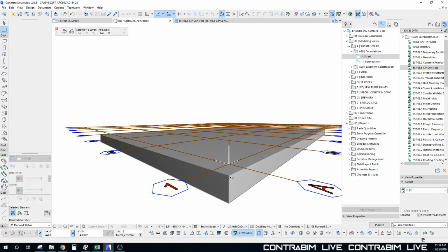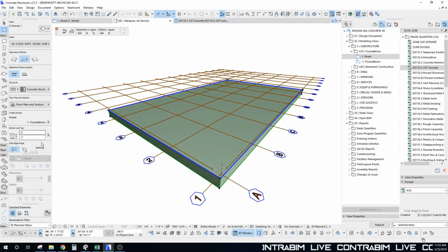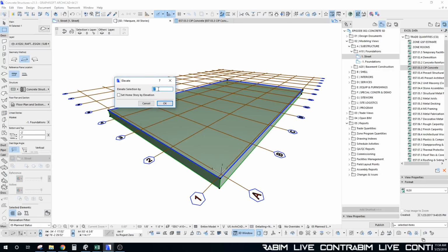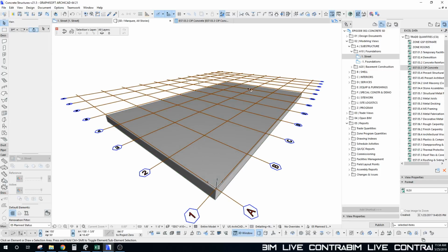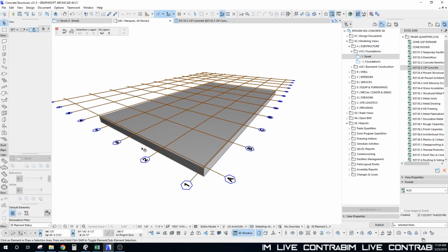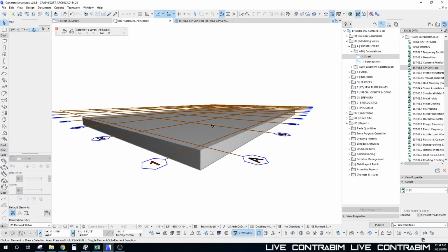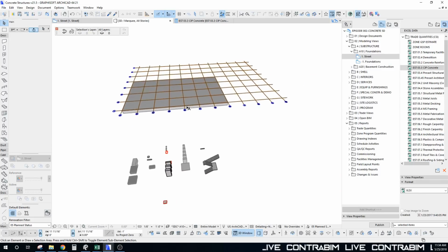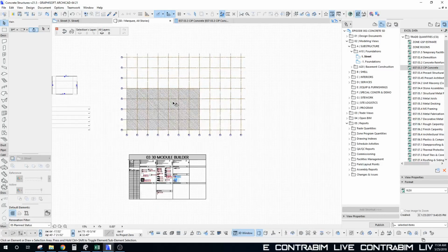So, okay, we can see here in 3D that we've just added that one mat foundation. And in terms of elevation on this project, we're going to set it 1 foot below finished floor. That's just going to be a nice clean number for extending all of our walls, columns, and different elements down to one flat elevation for our top of footing.